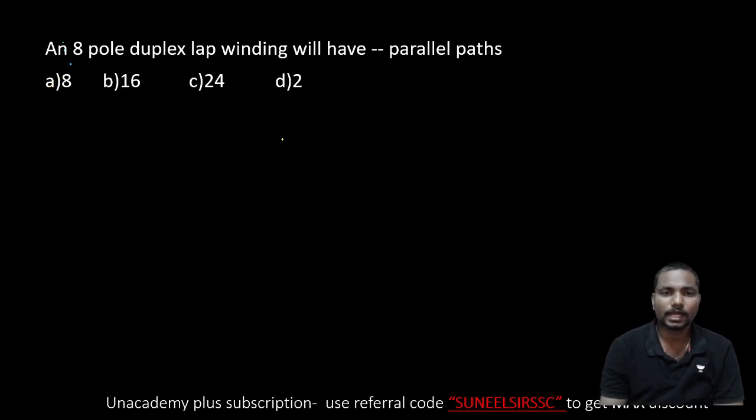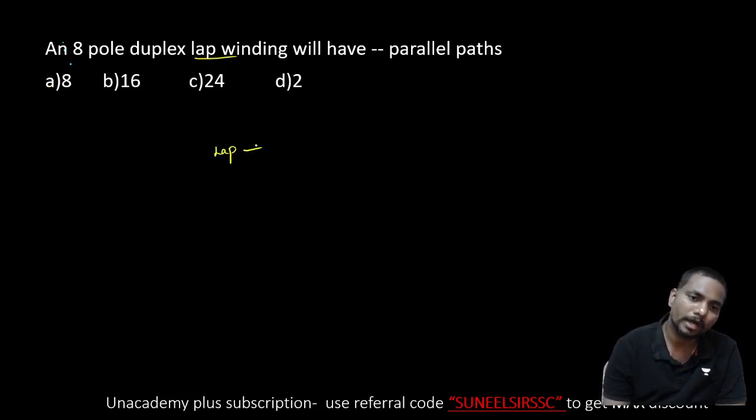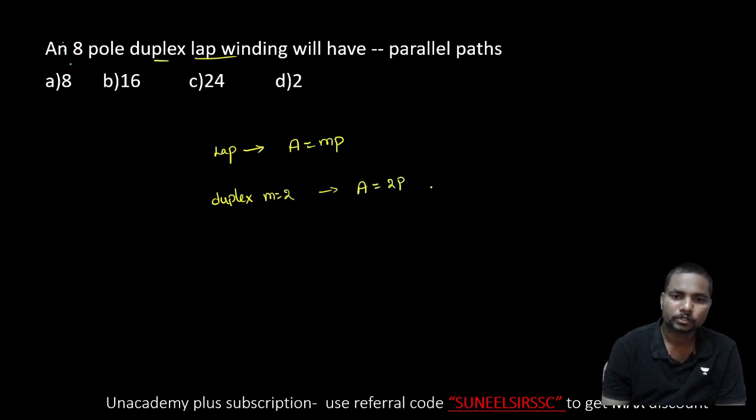Coming to the next one, again they have given lap winding. So whenever you see the lap winding, you have to use the formula A is equal to MP. And is it a simplex or duplex? Here it is a duplex. Duplex means M is equal to 2. So then A is equal to 2P. So that is nothing but 2 into poles 8, that is equal to 16. So the answer is option B.